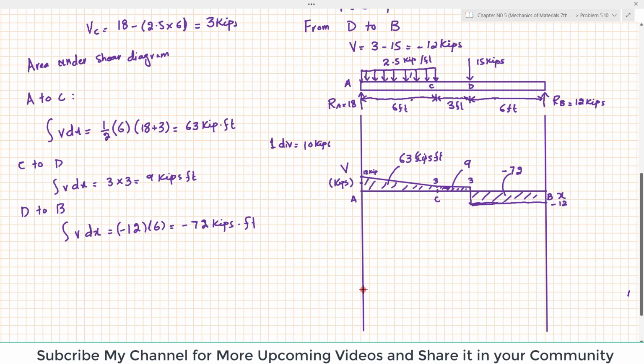Now we are going to plot the bending moment. Again, I have to take a horizontal line for the length. On the y-axis you will plot the bending moment, and the unit will be kips into feet. Here you have to decide, let one division equal 10 kips into feet.